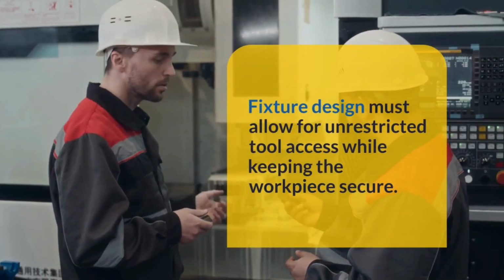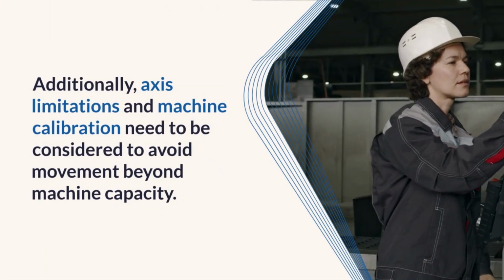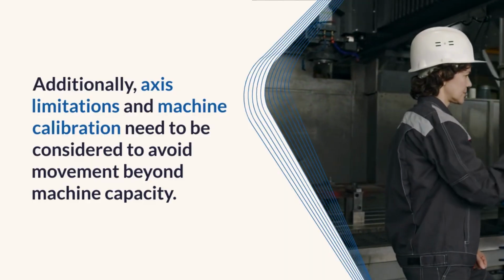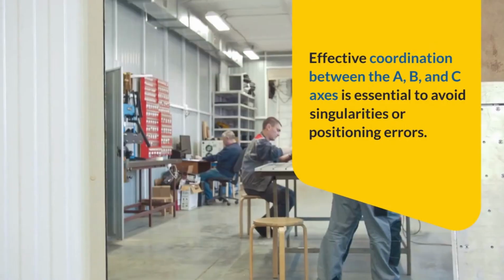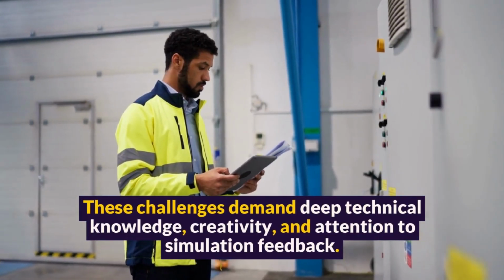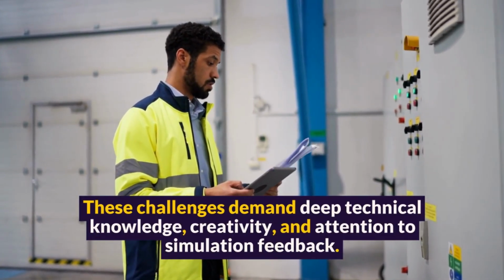Fixture design must allow for unrestricted tool access while keeping the workpiece secure. Additionally, axis limitations and machine calibration need to be considered to avoid movement beyond machine capacity. Effective coordination between the A, B, and C axes is essential to avoid singularities or positioning errors. These challenges demand deep technical knowledge, creativity, and attention to simulation feedback.